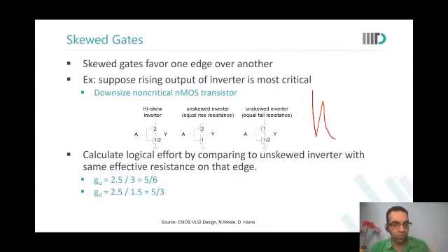You remember the skewed inverter thing? Yes, that curve shifts left or right. Exactly, that would happen. But that was impacting the noise margins. That is also impacting the delays. That is what I'm telling you. So how will that impact the noise margin? Because it will just shift but not change the slope. Now a very small disturbance on A will also cause output Y to toggle.